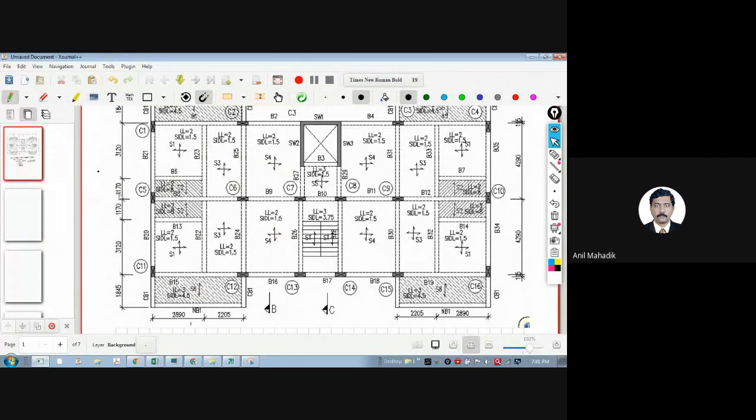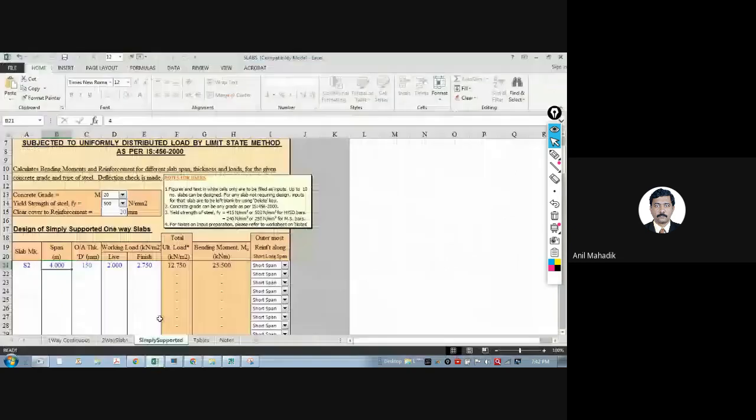Here you can see 1.17 meters. You can assume center to center. Whenever you design, no need to say, we have seen that manually, but you can assume center to center of this beam. In this case, it is 1.17 meters. So put the values here. Thickness you can assume 120, let's say. Live load is 2. And floor finish load, how much are we getting here? Floor finish means you need to add the sunk and all finish, whatever is there, which is 8.